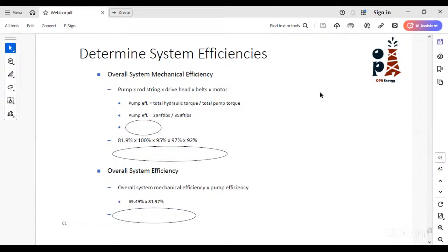You can also install something called a tubing rotator that makes 2 rounds per day, to distribute the loads on the different sections or different sides of the tubing during the day, so as to eliminate this severe effect of the friction between the rods and the tubing. So these are examples of the challenges that you can face when running your PCPs in unconventional wells.